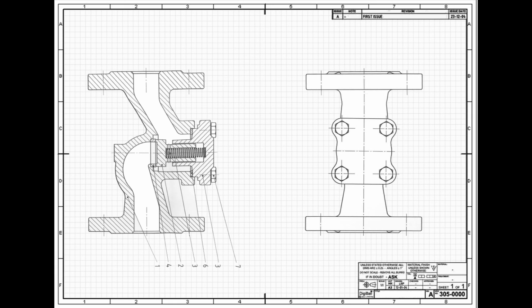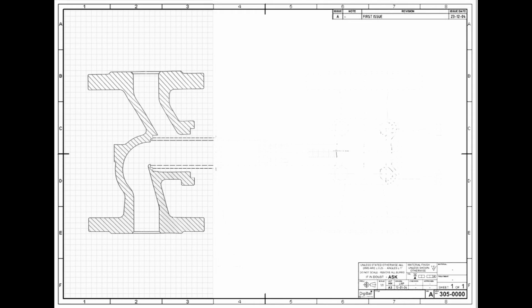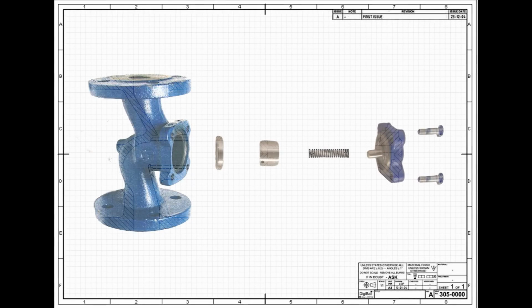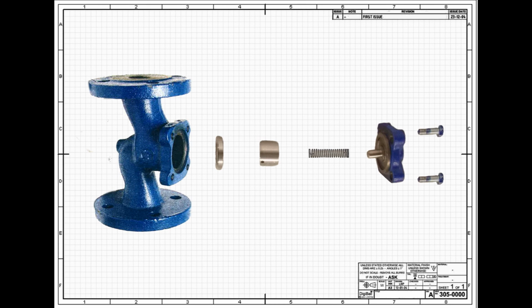Typically, these types of valves are utilized in the chemical processing industry and domestic irrigation. These devices are automatic and require no external activation. These valves are generally small, simple, and relatively inexpensive. A non-return valve consists of the following major components: housing, valve head, cover, spring, and hexagonal screw.